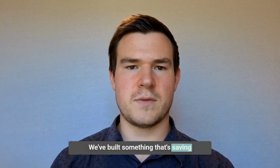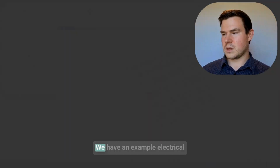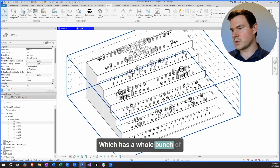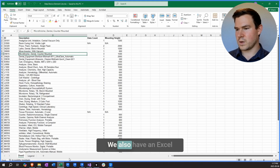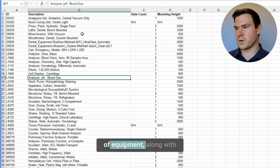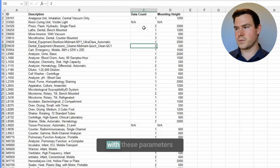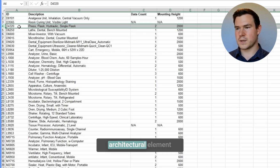We've built something that's saving weeks and sometimes even months of time on electrical Revit projects. We have an example electrical project open in Revit, which has an architectural link loaded in, which has a whole bunch of specialty equipment families that need data devices. We also have an Excel sheet which has a master list of these different types of equipment, along with some parameters for data count and mounting height. So what we need to do is place a data device with these parameters for each corresponding architectural element based